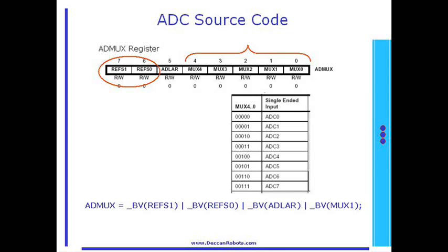Look at the single-line source code on your screen in blue text. This configures ADC channel number 2 with internal reference turned on to provide an 8-bit output. The converted value of the analog signal will be stored into the ADCH register in 8-bit format. The next screen will explain enabling ADC and starting conversion.